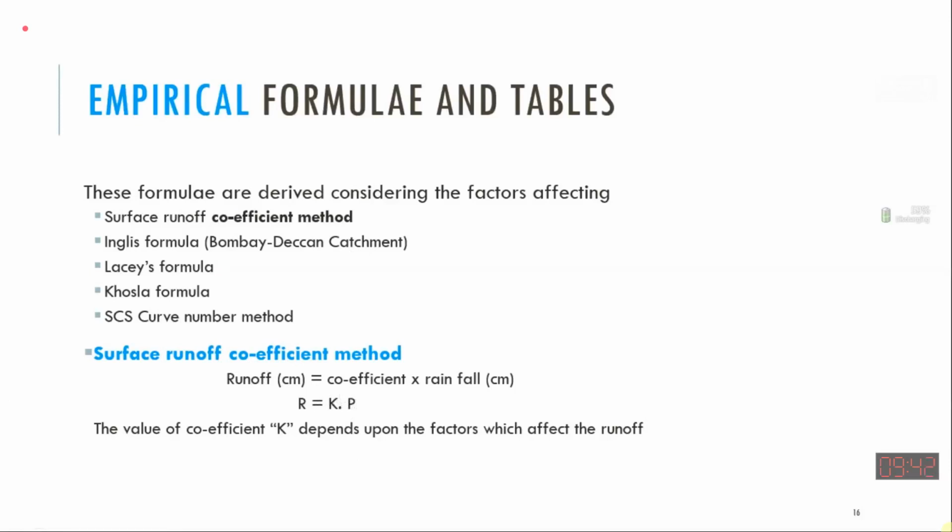The usual methods consider base flow and interflow constant in a certain catchment, so usually people don't try to estimate them with this formula. People try to estimate only the direct runoff, that is the result of the precipitation event. So they multiply the amount of the precipitation with the coefficient, and that coefficient they develop by seeing the previous behavior of that catchment.